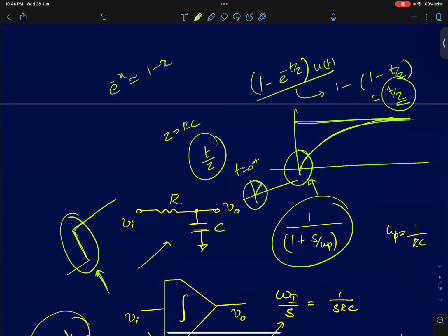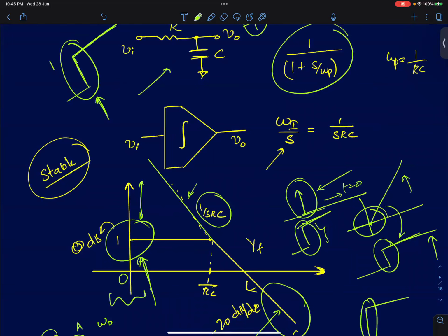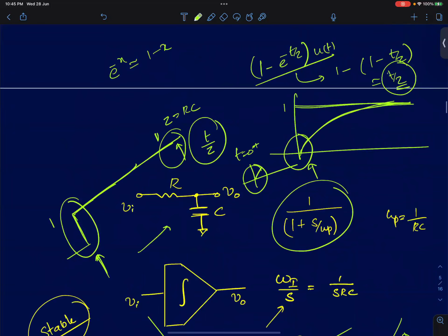The next step is the steady state behavior. Steady state is constant. The input now is a unit step function. So the DC amplitude is 1. The steady state, if you see, it looks like a DC input to the system, right? It's been 1 for a very long time. So the system will treat it like a DC input. So if the input is 1 in the steady state, you look at the transfer function, the DC gain is 1 or 0 decibels. So which means the input DC and output DC are the same, right? So you directly say output is supposed to be 1. That's it. So in steady state, you just say first order output is going to be 1. So that's it. We predicted this output.